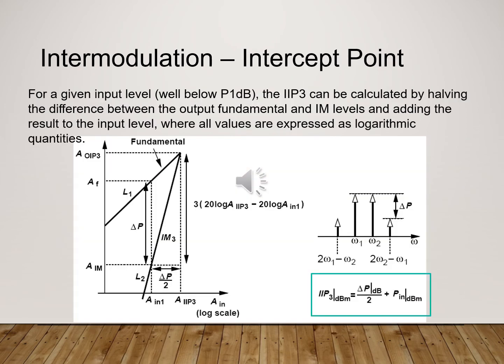From intermodulation concepts, one can define the intercept points: the input third-order intercept point and the output third-order intercept point. These points give us a range where the system is predictable and intermodulation is eliminated if the input level is below this point. But after that, the system will be useless and unpredictable, and intermodulation will occur.